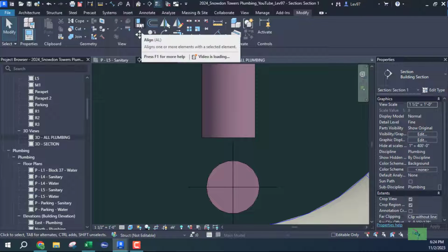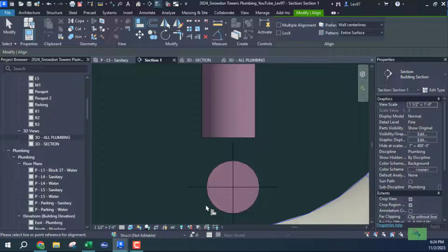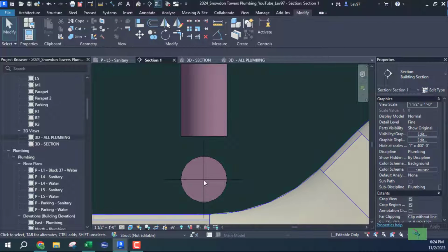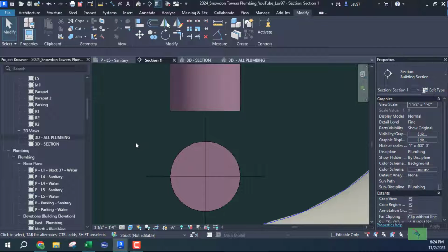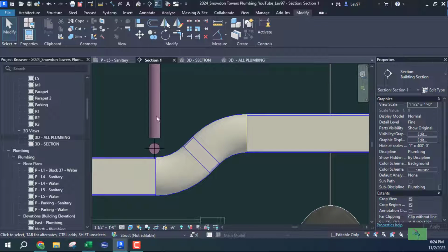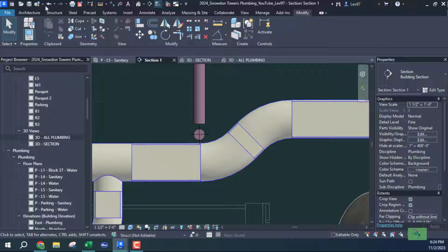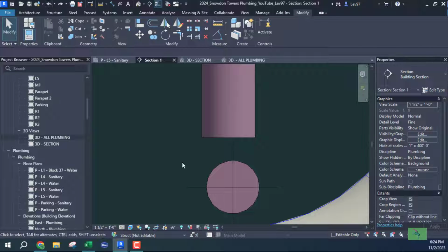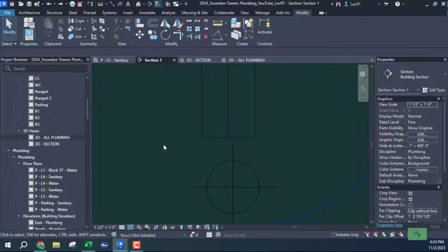Now, there's going to be a little dot right here that Revit allows us to align with the second pipe. So if I come to my align tool and go here, you guys didn't see that, but there's a small dot there that once you align it, you can see it. Let's back up. So it's not in line now. I think that the default is red.